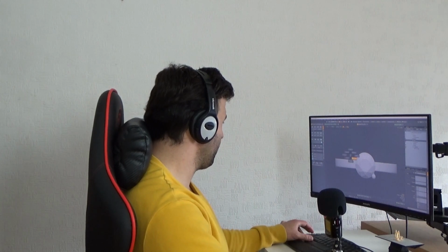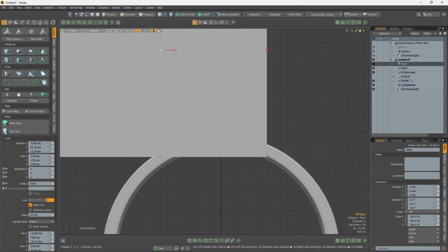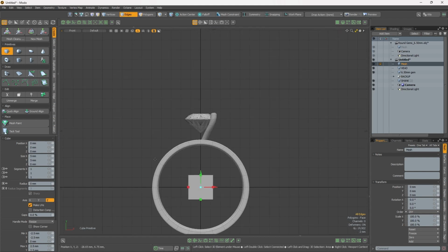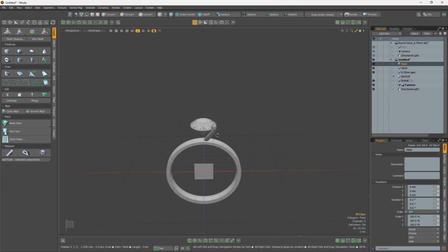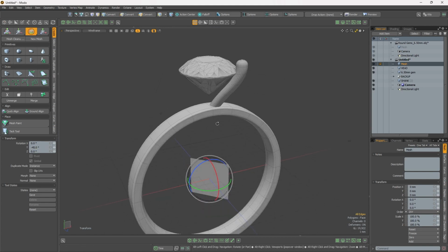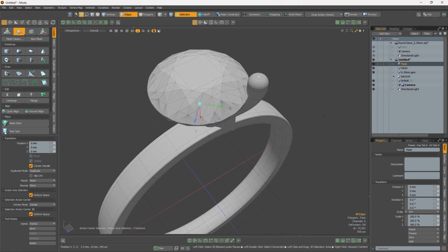But if you want to make sure it is at 45 degrees, even after creating the model, one of the solutions that now comes to my mind is creating a plane in the center, maybe 5mm, and then rotate it 45 degrees around the y-axis, or minus 45, and use it as a guide and reference.